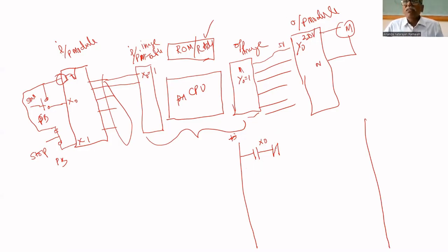This is a normally closed contact. Here it is like a NOT gate. For that, if I put it like this, this stop button will not work, because if you give 1, it becomes 0. If you give 0, it becomes 1. Because it's permanently giving 1.